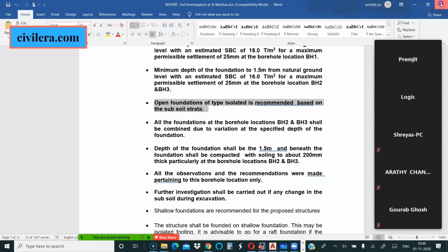One is, as I told you, it can save your client some money sometimes. Sometimes it can make your building safer by going with the soil report, because what you assume may not be the right thing to do. Third, as professional ethics, considering that you are a structural engineer and not a geotechnical engineer, please leave all the geotechnical scope to a geotechnical engineer. If you are qualified and experienced as a geotechnical engineer, then take that work up and do the soil exploration on your own.